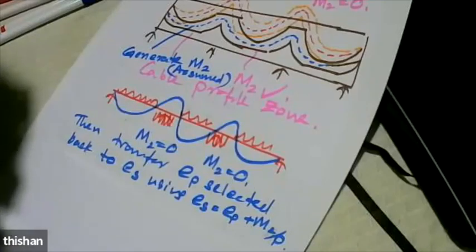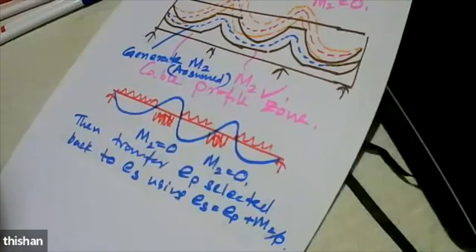Because we assume a value and we generate whatever we assume. But we assume something reasonable so that during construction, the beam will not become unstable. So we have to make sure we assume something between 0 and 80% of the dead weight. So that is the method.